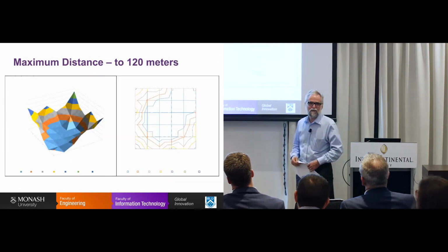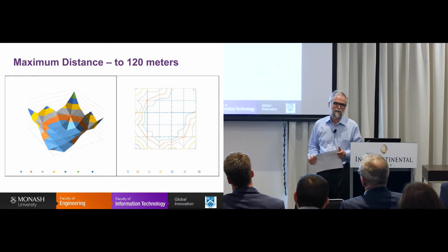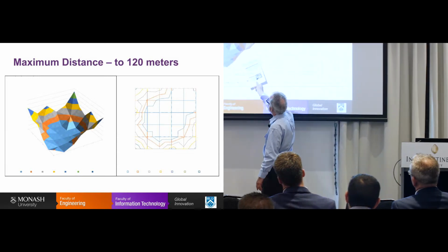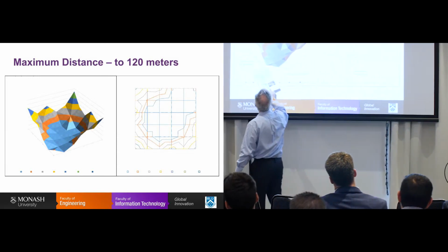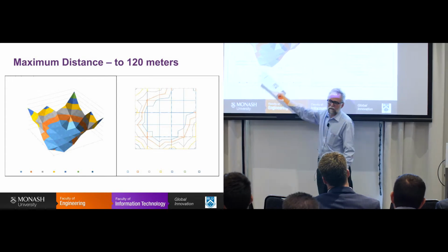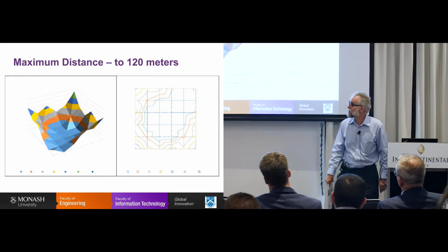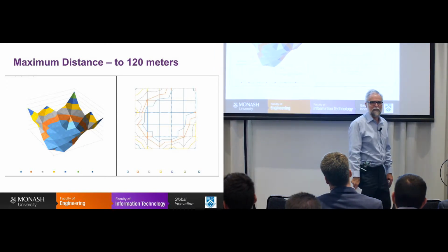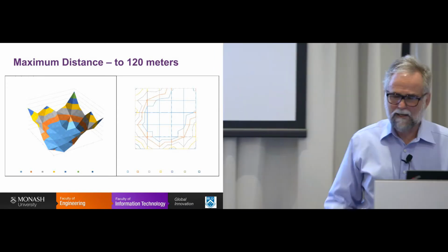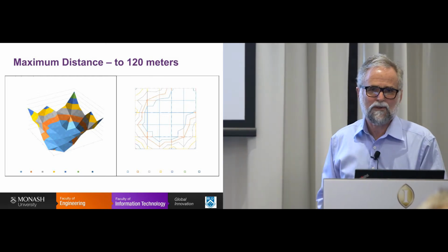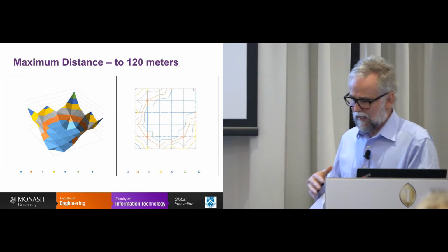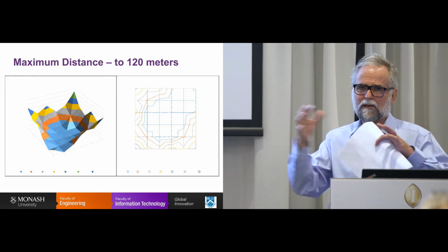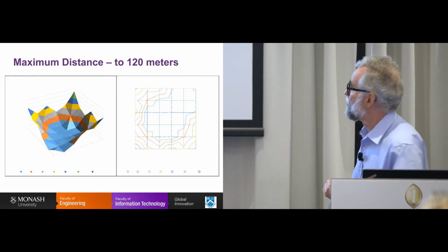This is a surface chart of the result of the maximum distance between houses. And this scale is small to high. So at the largest consumption levels, it's only worth connecting houses that are 20 metres apart. At that point, they're better off just having separate systems because at that level, you've got about 11 solar panels and about 2 batteries, so you can closely optimise the design.